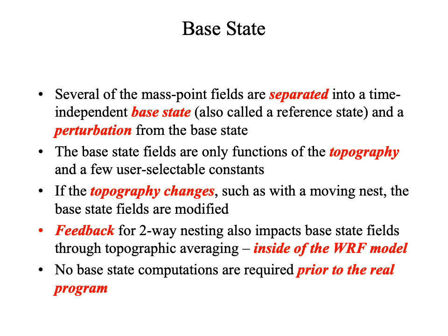The user, other than specifying these handful of constants, doesn't have to be bothered with the construction of the base state or the perturbation state. When there is feedback turned on for nesting, there is a mandatory consistency between topography on the coarse grid and various coincident points on the nest.